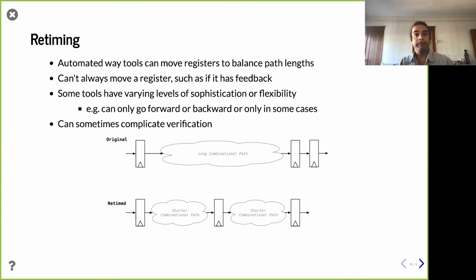And so because retiming has been around long enough, people are aware of this. Some of the ways they can deal with this are things like, even though you've moved this register and now it represents a different portion of the design, using formal verification to prove that the values here are consistent with the values they should have been if this register was still over here, for example. And so how to establish these equivalences, even though I moved these registers around, which one's supposed to hold which values in which cases. Like I said, you made verification's job harder, but once again, push things onto the tools, out of humans' hands. There you go. Questions?